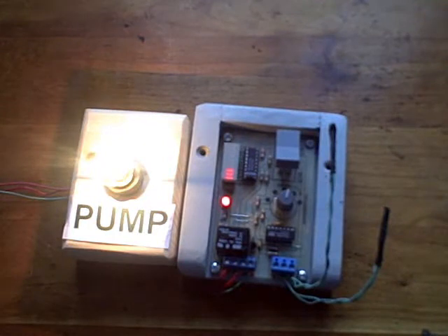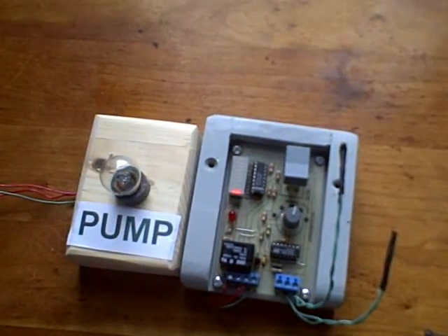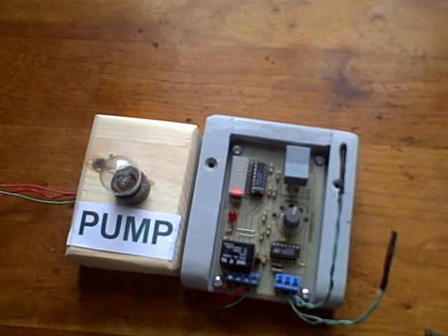So now the differential is 15 or 20 degrees higher; the collector temperature is 15 or 20 degrees hotter. And then it takes a little longer to turn off. And that's what we want. The differential off setting should be much closer to the storage tank temperature.